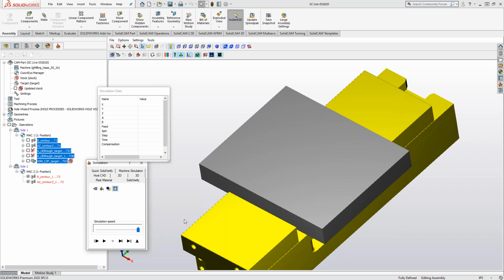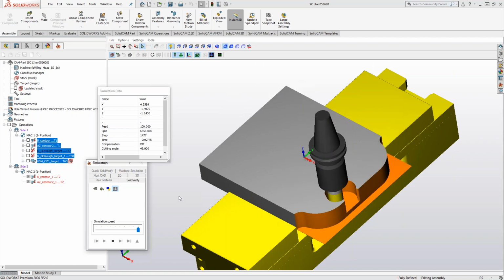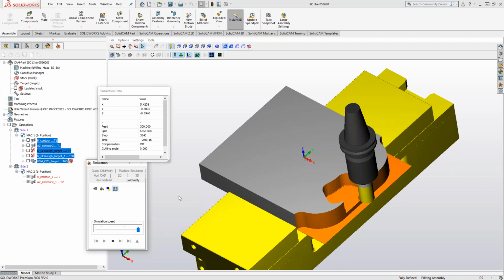So all those different scenarios that Kevin's been bringing up would require different toolpaths, because in some you want compensation, in some you're just going to set the wall offset to 0 and just get it done anyway. Some don't even need roughing and finishing. We were talking to a customer earlier this week who was doing some sort of fiberboard kind of material, and he doesn't even require a roughing versus finishing. He just goes right down to 0, and it does all his wall offsets at 0. So a lot of the time you look at these toolpath lists as just toolboxes. Basically, they just have a bunch of toolpaths in there. You choose the best one for the application.